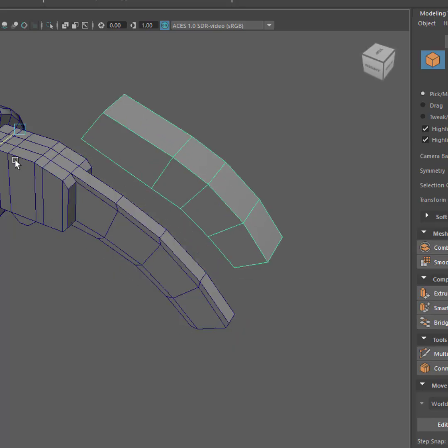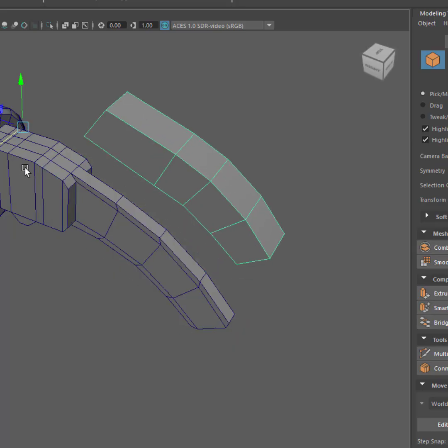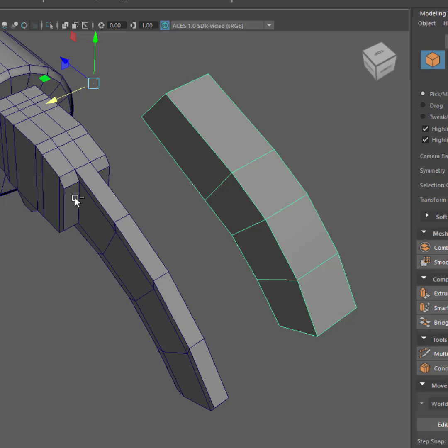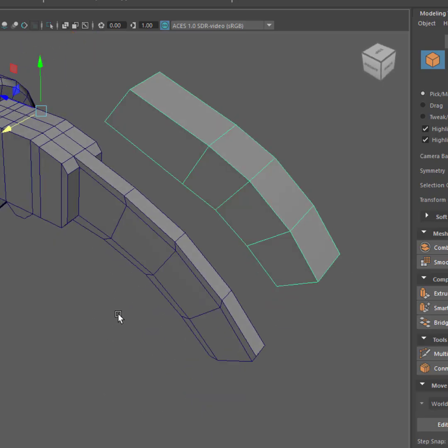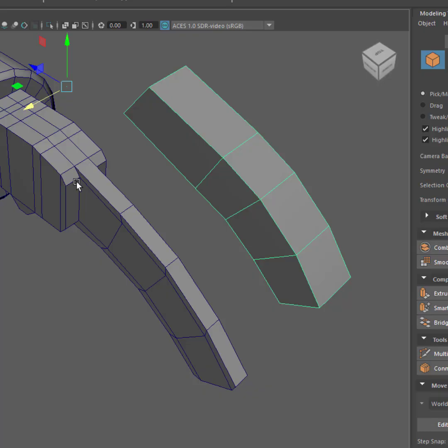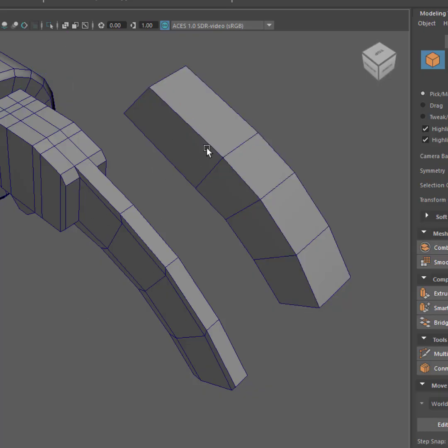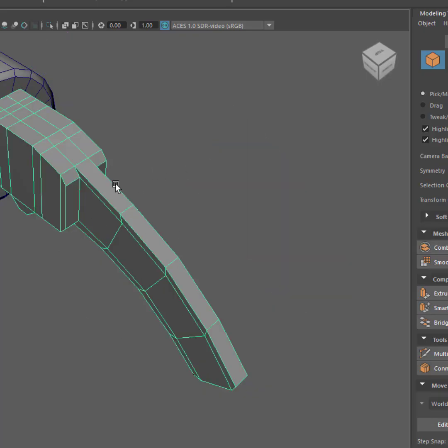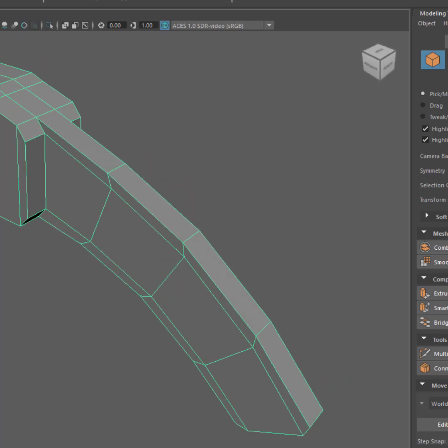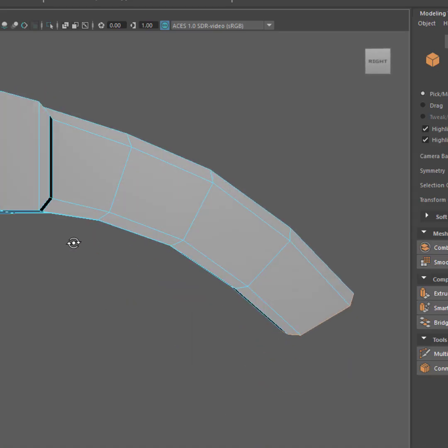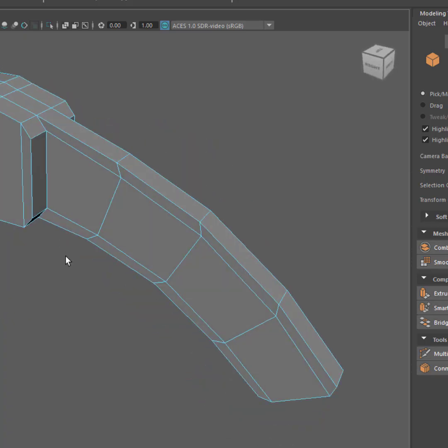If I bring out the other objects, this means I do not need this initial object that I've created earlier, but I do need the wooden parts here so I can model them. So I need to model them precisely. What I'll do is select this, delete that, select this, and then start by turning on the face selection or polygon selection, pressing Q just to select properly, and then I'll select these sides so that I can create objects precisely in such positions.